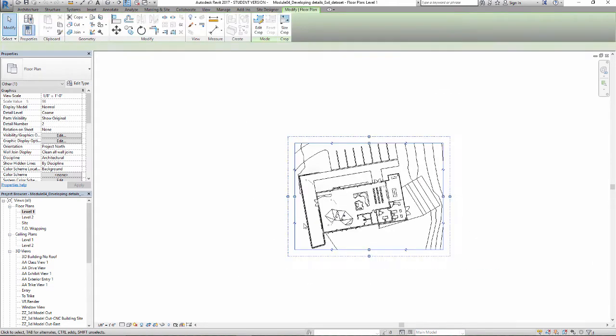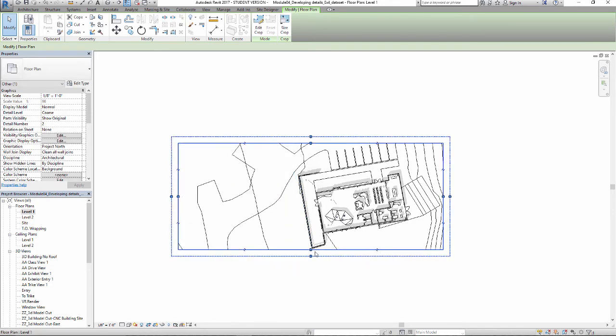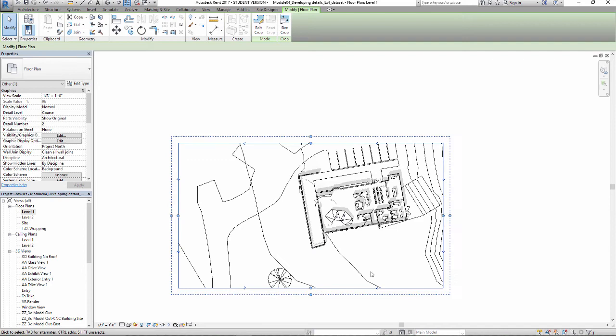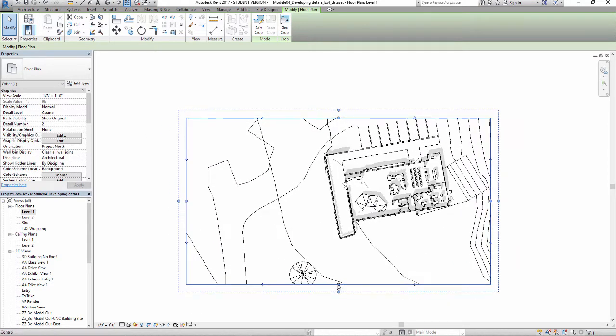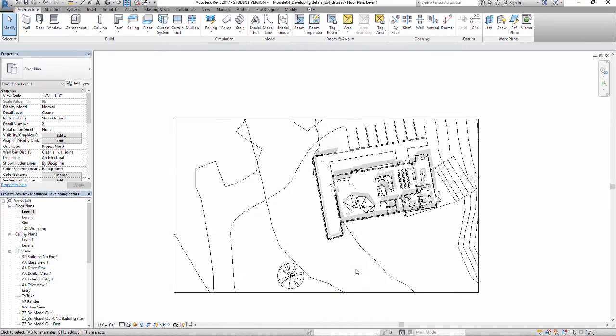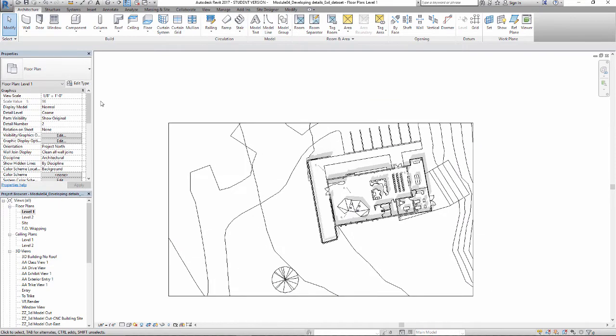And I'm going to take a section perspective, build a section perspective looking this direction. And this is not a really complicated building. So I'm not going to get any wild results, amazing newfound things by doing a section perspective. So it will give us an idea of looking at these specific techniques. So the first thing that I need to do is set up a camera view.